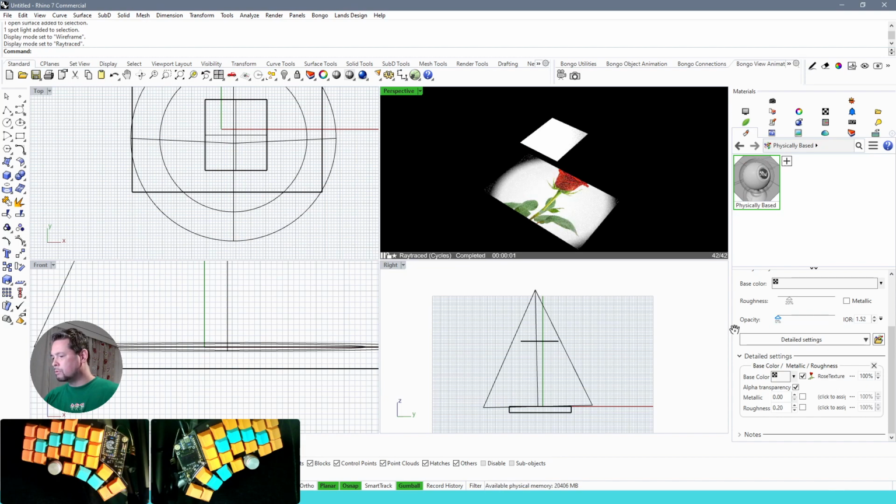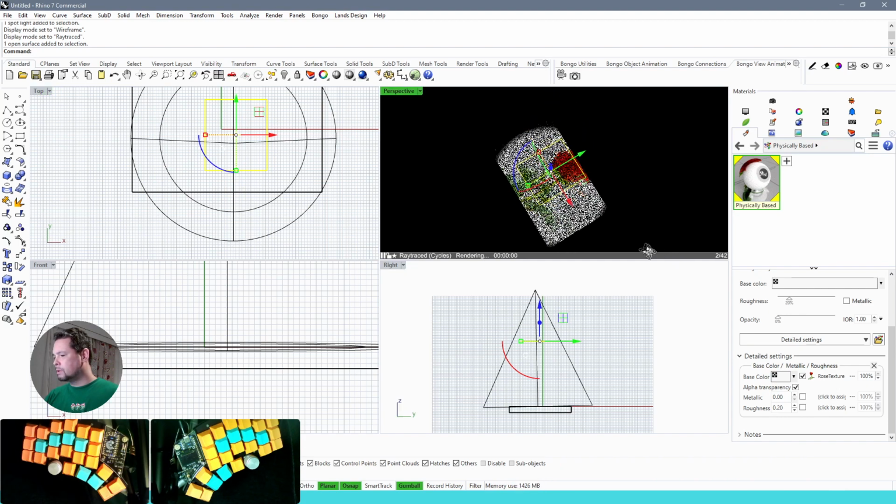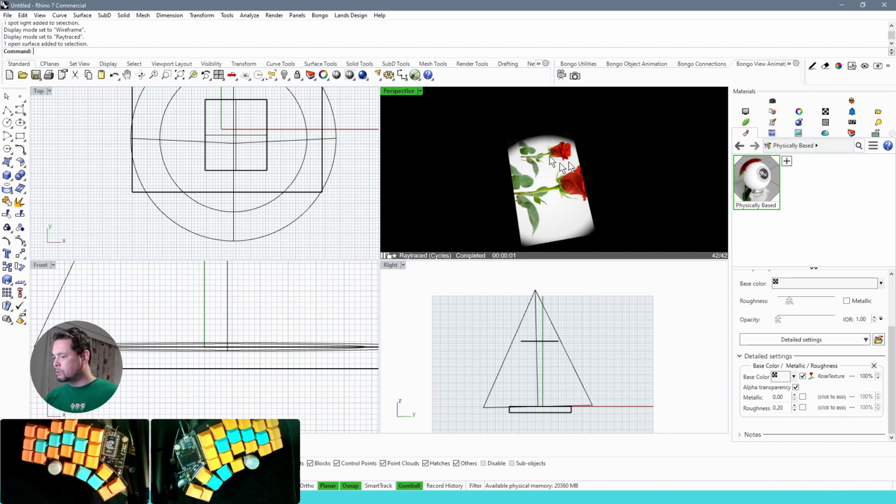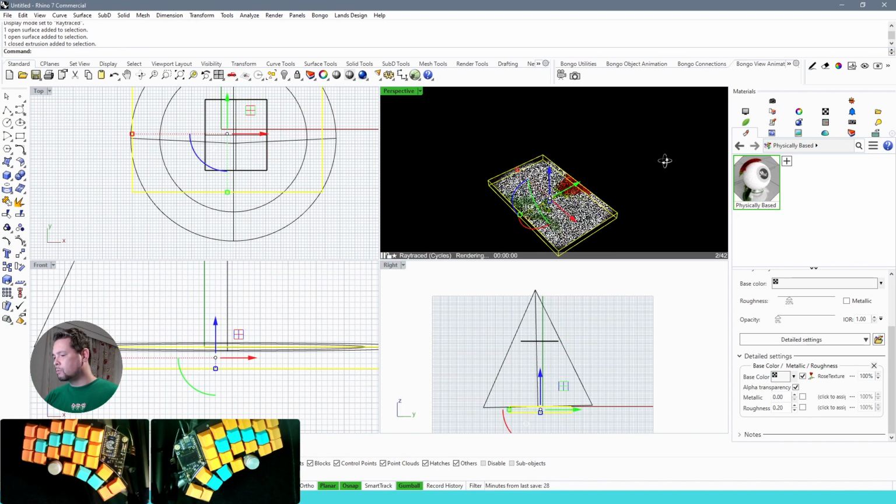Opacity we're going to turn down completely. And actually, since we're not really interested in the IOR part, I'm going to also set IOR to 1. So now we have the image from the textured surface projected on wherever our light shines. So let's see, we have both now completely visible. So this is the texture with the original image on, and this now has the projected one.